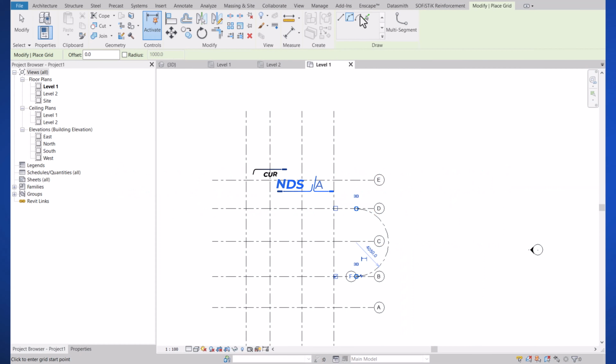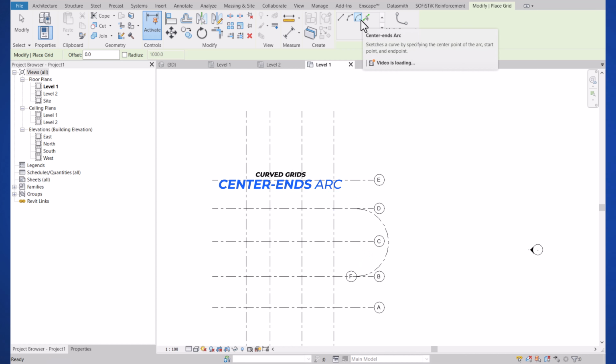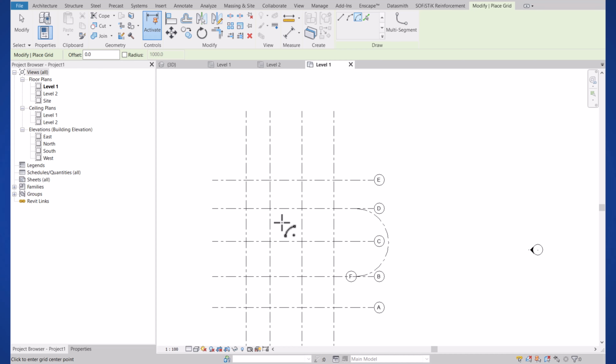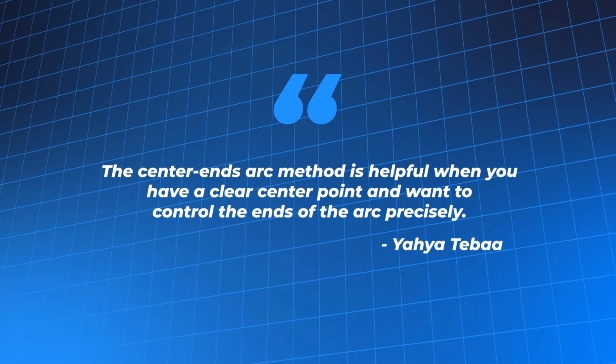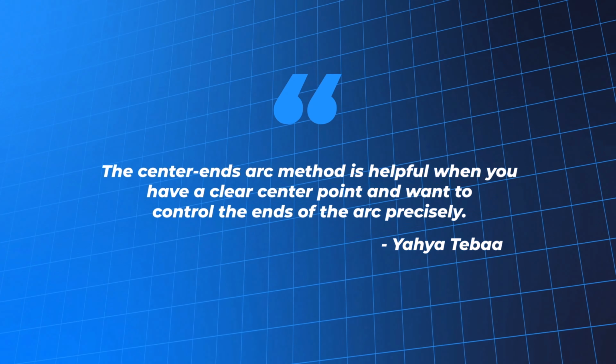The second tool is called center ends arc, which goes this way. First, we click to place the center point of your arc. Move the cursor outward to place the first end. Then continue to place the second end. This method is helpful when you have a clear center point and want to control the ends of the arc precisely.